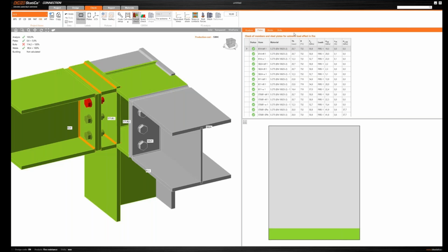in more depth, where in the plates we can see, for example, summary of the results. And we can see that the magnitude of the yield stress is very low due to the high temperature. So we have a 50.8 megapascal yield stress in this case.